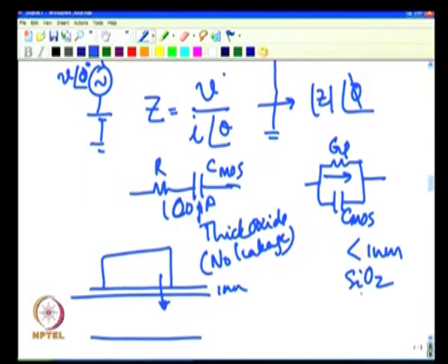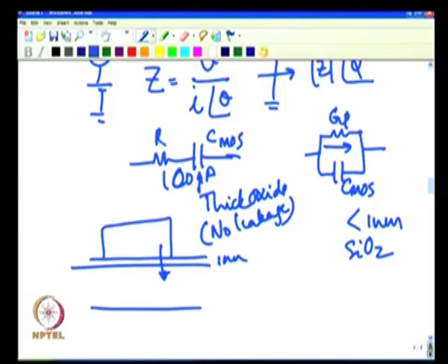You tell the equipment that this is a more realistic model to use, not this model. If you do not follow this, then you will actually get an incorrect result for your capacitance. In fact, I will leave this as an exercise, you can do it yourself: if you were to do this kind of an equivalence, you see that when R is not 0 and this is not infinity, your capacitances in these two cases will not be equal.